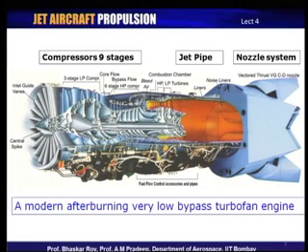So, that you have 2 loops there, one which we call the HP loop, another which we will call the LP loop. And then of course, after that it goes into this hot zone, shown here as red zone, which is where you have the reheat or the afterburning, and then you have these liners all around it to protect the outer shell of the engine from these very hot gases.